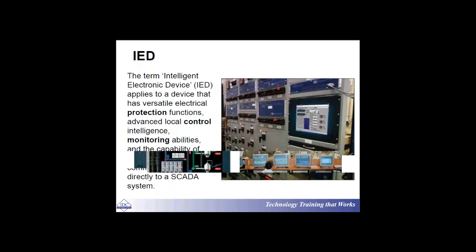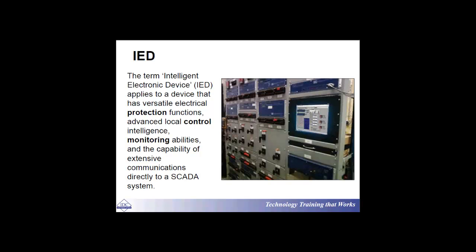Then we have got the concept of IEDs. So previously, engineers and technicians used to refer to protection devices as something like relays. But these days, these kind of things are mini computers. They are multifunction. They are not only protection, but are also capable of being connected to control gears, intelligent control gears, monitoring devices, metering devices, other Scada RTUs, PLCs or something.